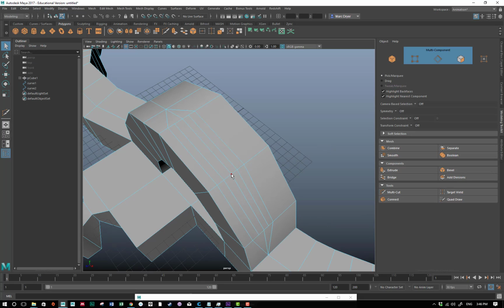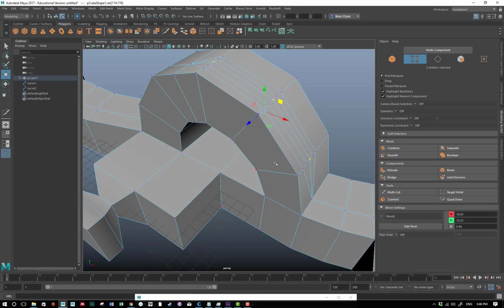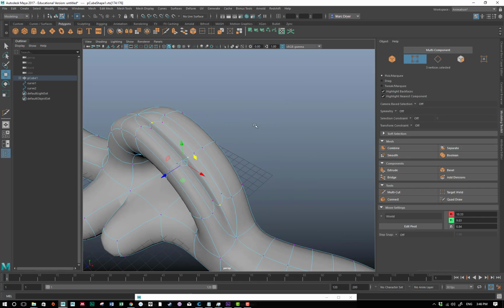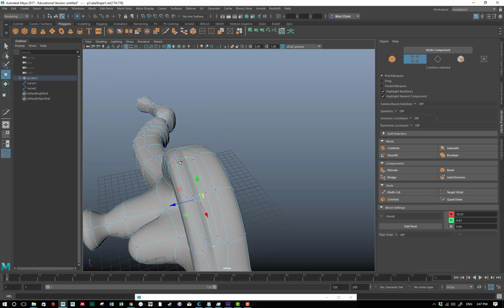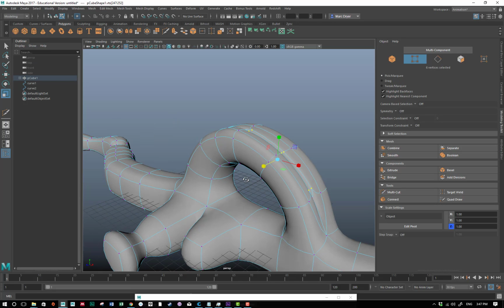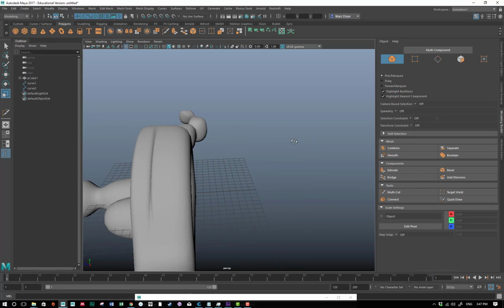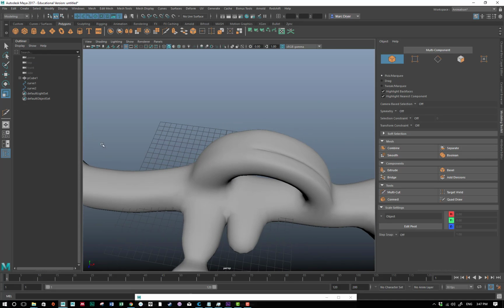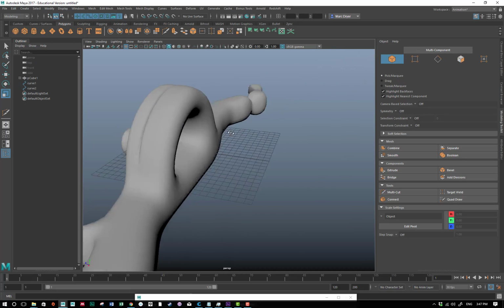So get out of the tool just by hitting Q. So if I select these central vertices here, this new cut that I made, if I go into W to move, I can move these down. Then when I go into smooth mode, I can kind of make a little wrinkle here, and if I have this geometry, selected the surrounding vertices, and I can scale these together to actually model in a little local wrinkle without having to put an edge loop that travels all the way around.